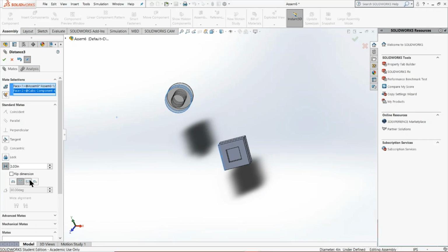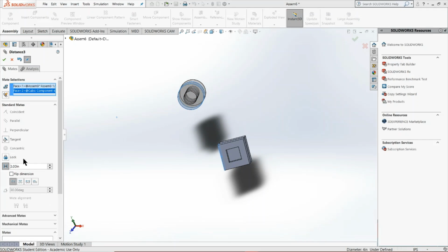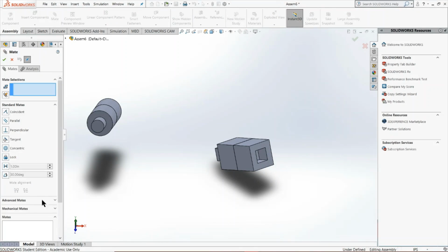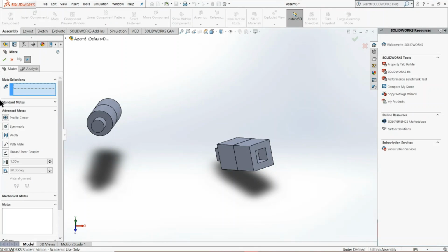But you could change that. It is entirely up to you. And the same thing applies for angles as well. So say if you have two objects that you want at certain angles from one another, typically works with planar surfaces a little bit easier, you use the angular mate. However, now we're feeling a little bit more spicy. We're going to move on to the advanced mates.